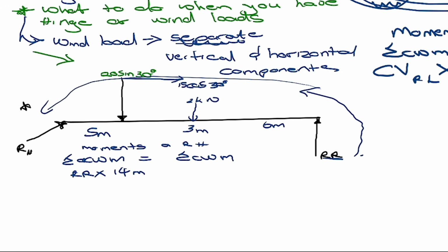Okay, cool. Now you need to find out any other force that is moving in the anti-clockwise direction. Let's find any other force acting in the anti-clockwise direction. When you look at number 3 there, the 2 kilonewton, you will realize that it's coming down on this side, so it's in the clockwise direction. And then when you move on, before that, look at the horizontal component of this 20 kilonewtons force that we assumed would be there. Look at what is happening. It is moving to the right, so to the right is like moving clockwise.